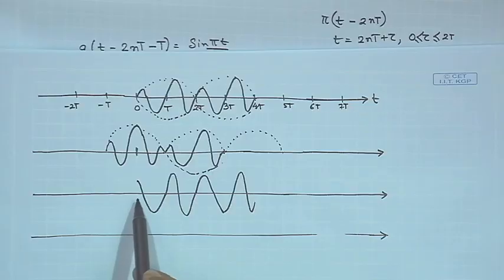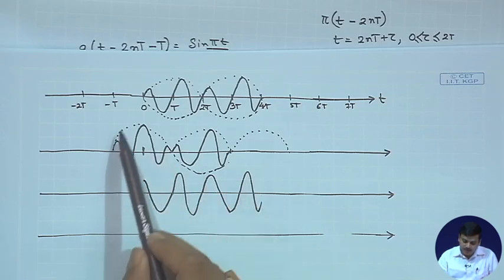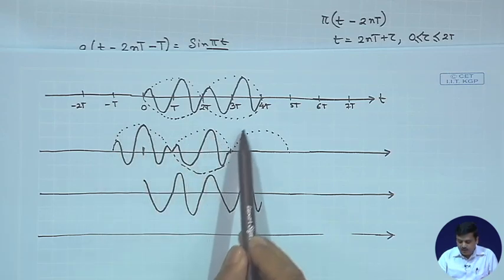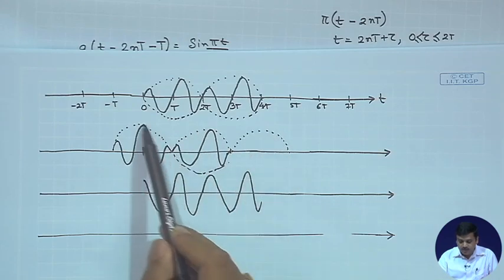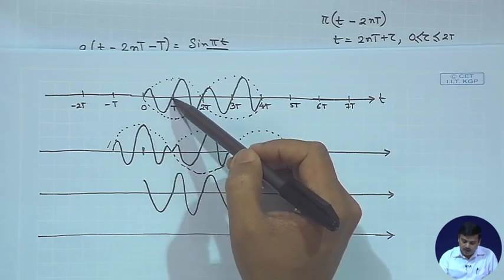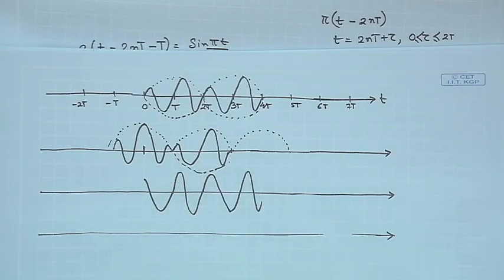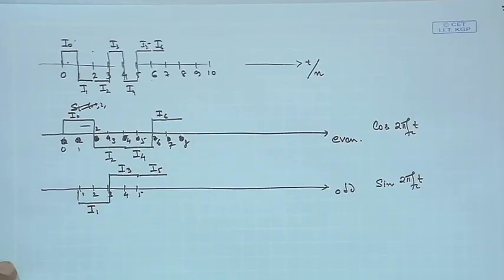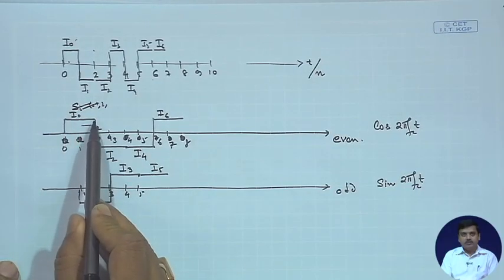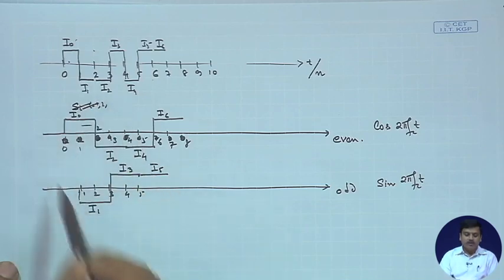So, as if you are getting two different frequencies. However, since you are doing an FM, there is a continuity of phase, and this has primarily been because you are using a pulse shape which is non-rectangular, and each of the non-rectangular pulse shapes is modulating a carrier in the in phase and in the quadrature phase, and they are taking the input bit stream, dividing it into the in phase and quadrature phase. In order to maintain the bit rate, you are stretching the even bit stream to 2t duration, you are stretching the odd to 2t duration. So, that overall bit rate remains the same.